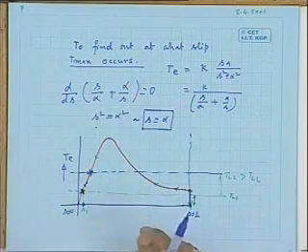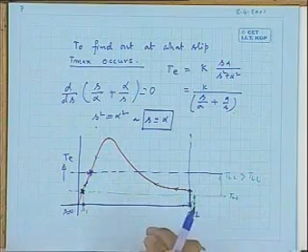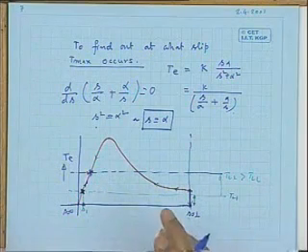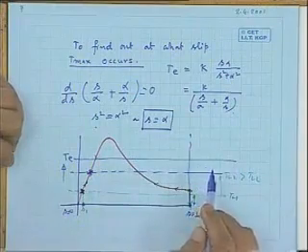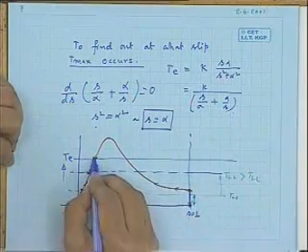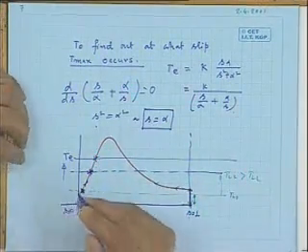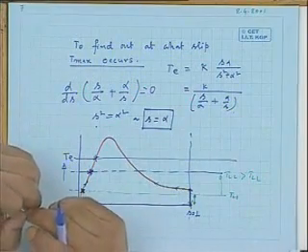And finally, it is at this point that once again the machine will find a stable operating point, because once again the electromagnetic torque developed by the machine is equal to the load torque, and the machine will run steadily here. If you further increase the load torque, finally the machine will come here.